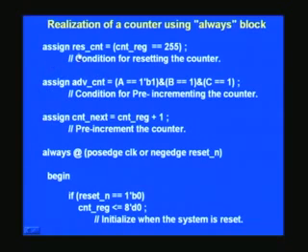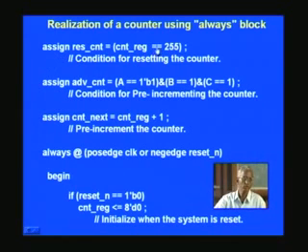So we have seen that reset counter is when the counter register is equal to 255. Once again, we notice that two equal signs are used here, being a logical statement. What it does is the comparison, and if the comparison is true, then 1 is output, and that 1 only is assigned to this reset count. Is that clear? It is not the 255 that is coming over to this. This is only a single bit. The result is a single bit once again, which is assigned here, and it's all based on the counter value as such, and that's what we have written here as the comment.